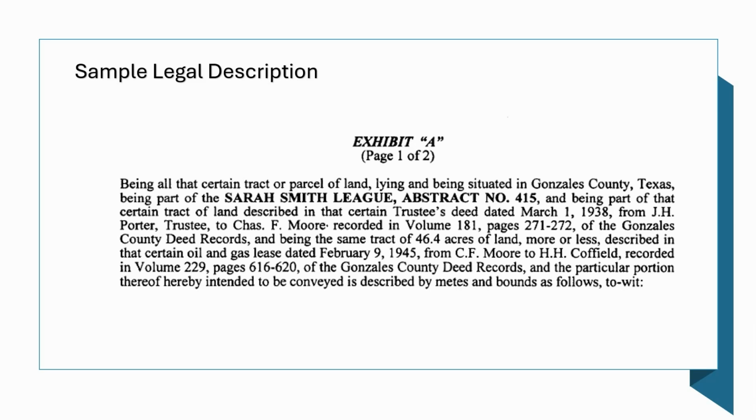All right, so to start going through this legal description, I have it broken up into a series of sections on several slides. We're going to go through this entire legal description together, and I'm going to point out where we have specific information that's going to be relevant for you as the surveyor, and for us specifically in this course as drafters. So let's begin. This is Exhibit A. We know the total number of pages that are going to be a part of this. Sometimes that's helpful because courthouses flood, courthouses burn down. Sometimes we have missing information, and to know how long this is supposed to be can be surprisingly helpful.